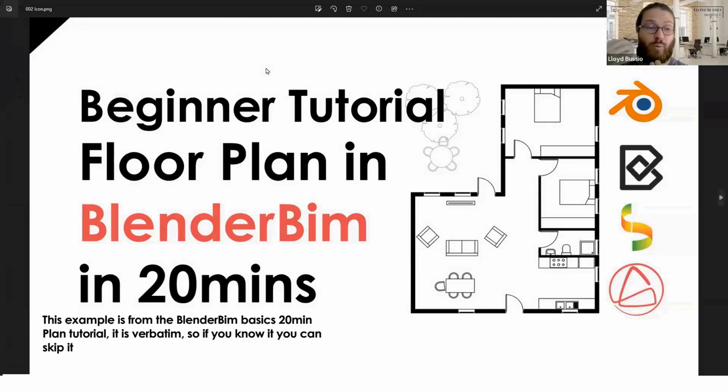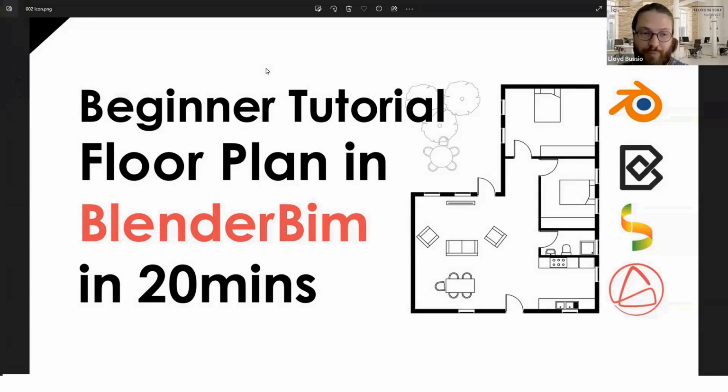So the reason I wanted to start this CPD to get people introduced to this is because BlenderBim is quite a powerful documentation tool. It takes an IFC file, which is, as I mentioned, an international standard, which means any AEC, architecture, engineering, construction program can open an IFC file, which means whatever you make can be transferred, at least the geometry, to another program. So if you're coordinating with engineers, or if you're coordinating with other architects who use different programs, it's much easier if that's in IFC than in a native Revit, ArchiCAD, Rhino file.